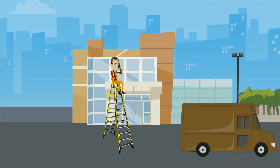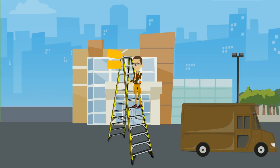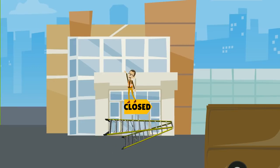Never sit or stand on the very top of a stepladder. In fact, the recommended rule by stepladder manufacturers is to never stand on the top two steps. If your knees are above the top of the stepladder, you are too high on the ladder.